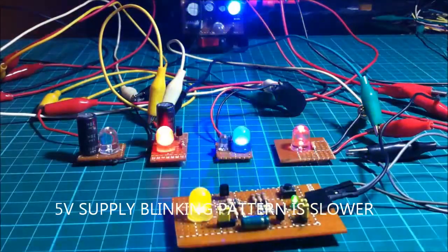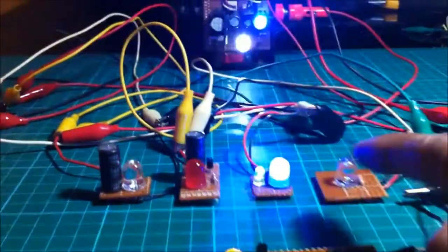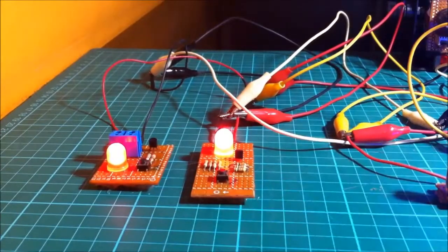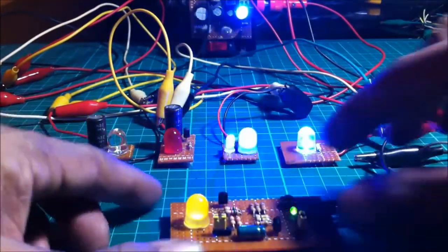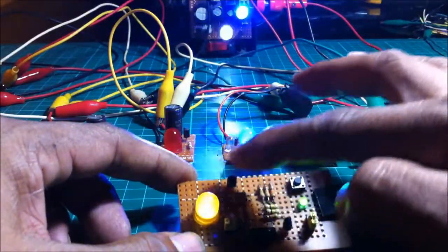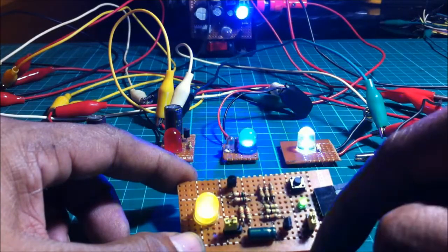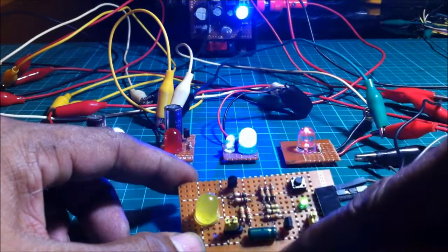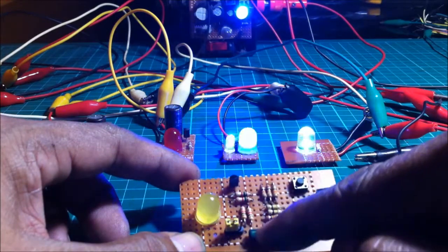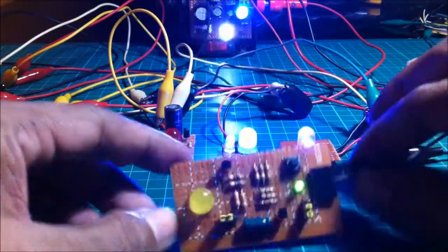So now we have one circuit, 2 in 1. An LED flasher and at the same time a manual switchboard, using 2 NPN BJT transistors. I'm using 2N3904. Also, only one capacitor and some resistors.